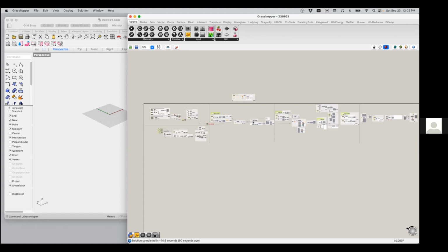So if you were working with a design team that involved you from the early schematic times, you could use Rhino to feed information to both BIM and the energy calculations, but you need to do that from the start. Potentially, even the teams that we've been involved with from the start, though, it has been challenging to get the data that we need encoded or embedded in the model. I mean, even something as simple as room by room ventilation flow rates, even just getting teams to add that much data to the models has proven really challenging. And we haven't had a lot of success, even with teams where we're involved from the earliest stages.